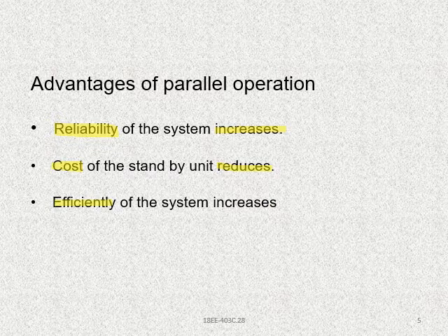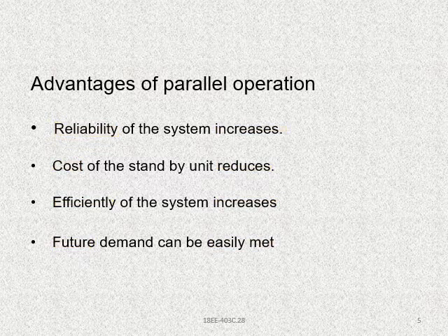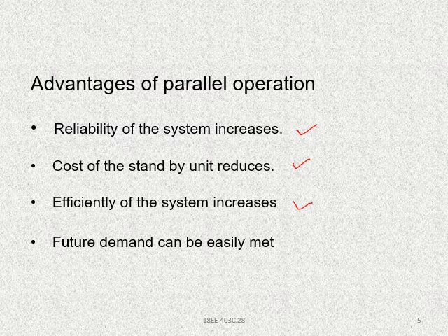Efficiency of the system increases. Future demand can be easily met. Please make a note of them. Reliability of the system increases, cost of the standby unit reduces, efficiency of the system increases, and future demand can be easily met. So these are the four advantages of parallel operation.